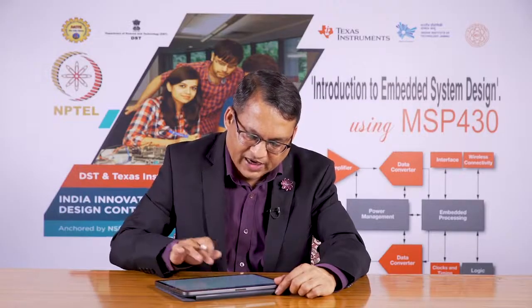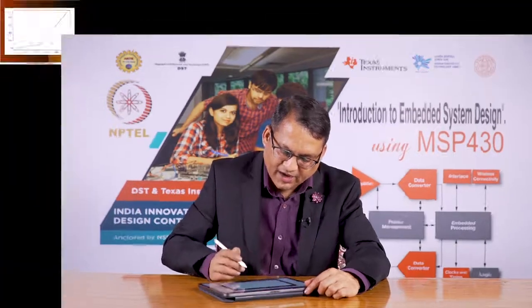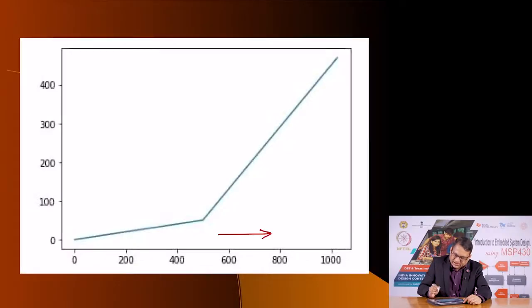And so, one way would be to apply some non-linearity, some mapping of the ADC values in a non-linear fashion, so that I can have a different amount of delay. And one method could be, as illustrated in this graph, where on the x axis is the ADC value, and on the y axis you have the delay time.